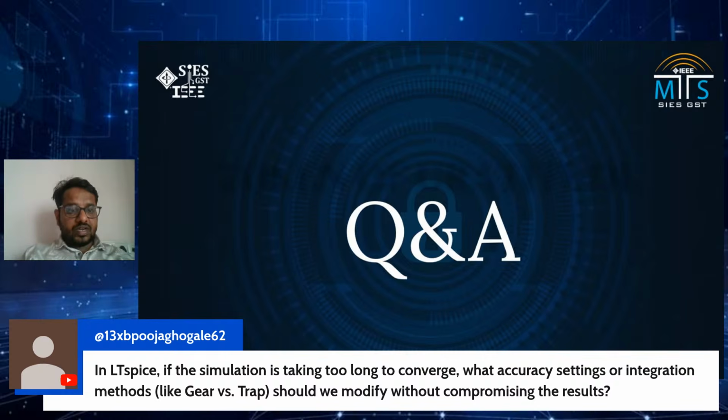If your model is correct, then it will not take much time. But there are other things, like if you have very high switching frequency circuits, then it also takes time. So here there is a way: you can divide the circuitry and try to model it with alternative circuitries, which can reduce the simulation time. Okay.